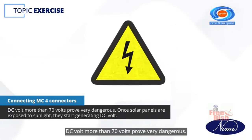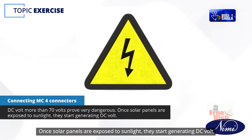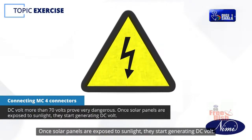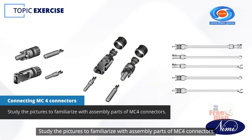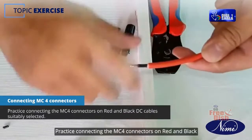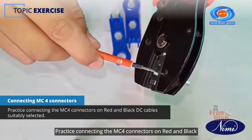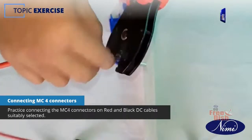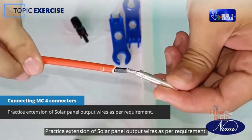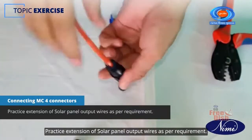DC voltage more than 70 volts proves very dangerous. Once solar panels are exposed to sunlight, they start generating DC voltage. Study the pictures to familiarize with assembly parts of MC4 connectors. Practice connecting the MC4 connectors on red and black DC cables suitably selected. Practice extension of solar panel output wires as per requirement.